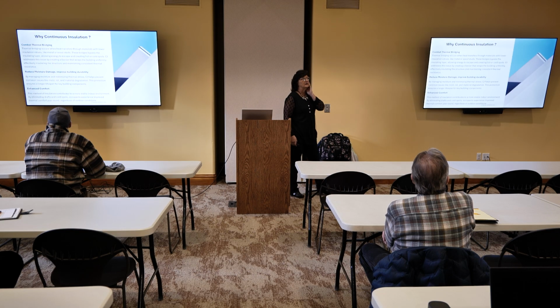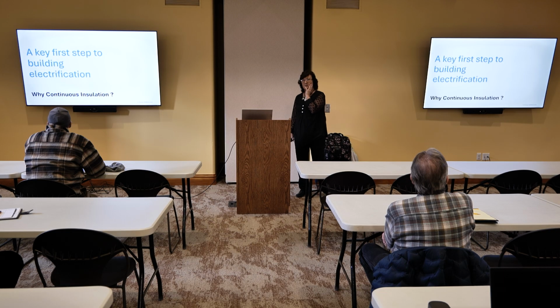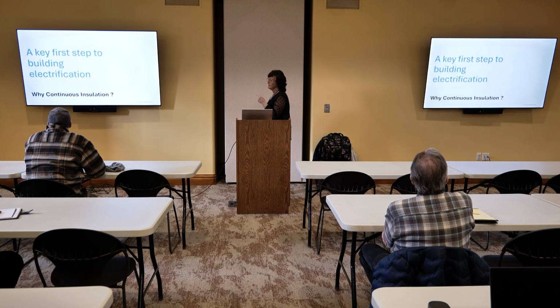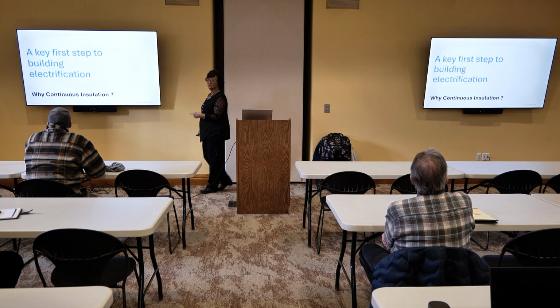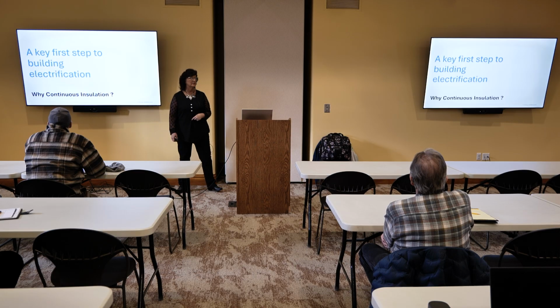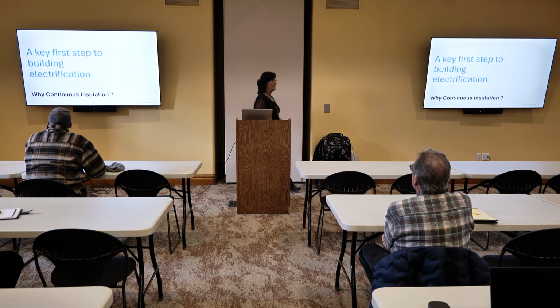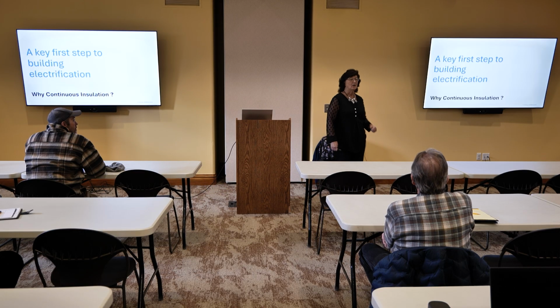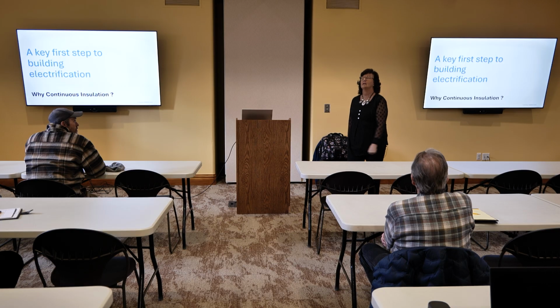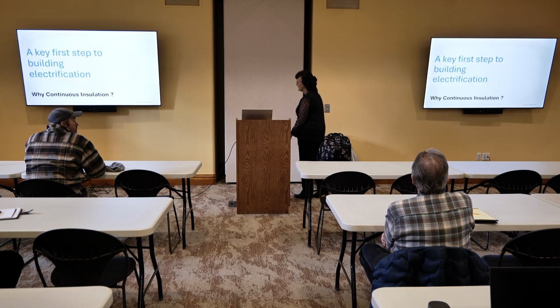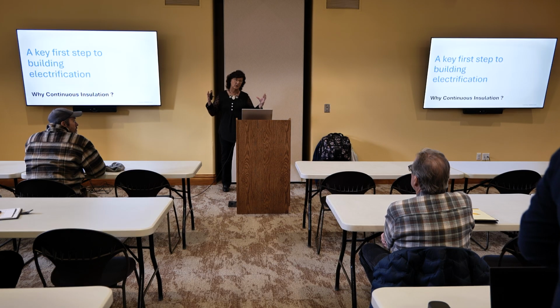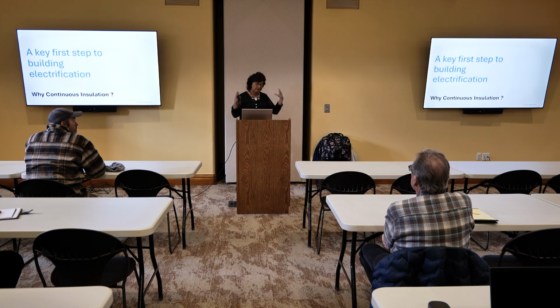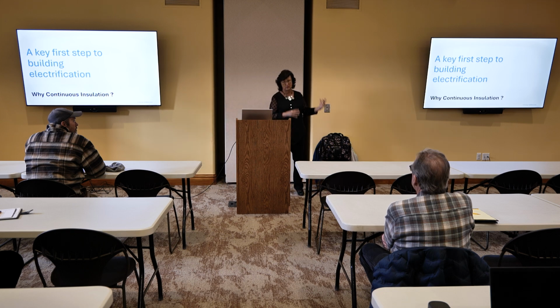Another reason that people aren't thinking about is a lot of people are heading towards building electrification, right? And this is a battle that I had with City Council in Aspen, right? They wanted us to be all electric when we adopted the 2021, and I'm like, heck no. We've got to get the envelope down first, and a really good envelope, so that when we do go all electric, we're not taking such a huge load, right? And so we have a lesser load,